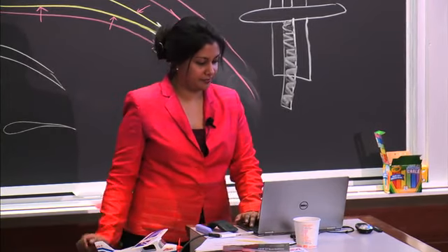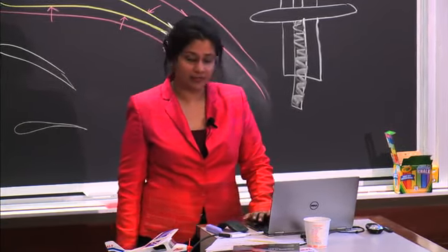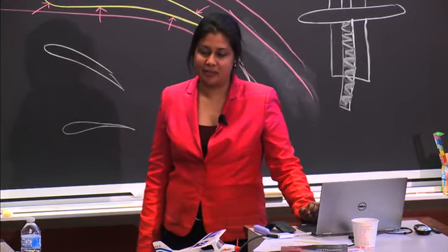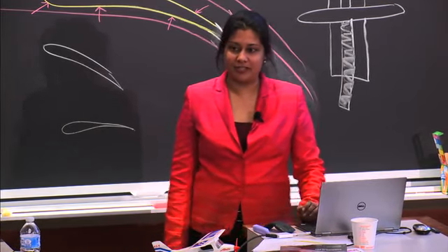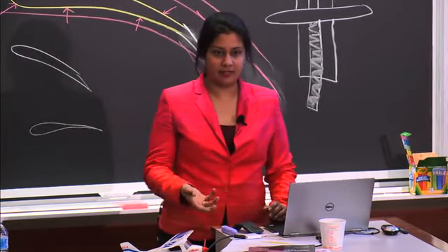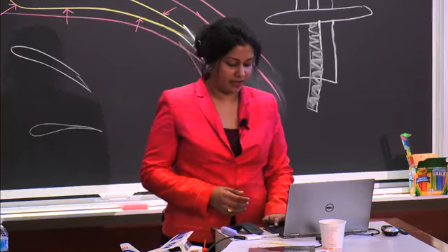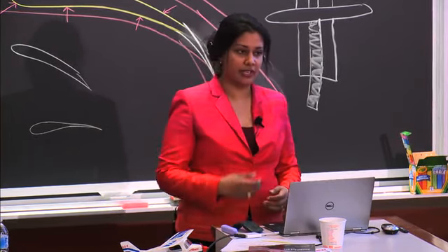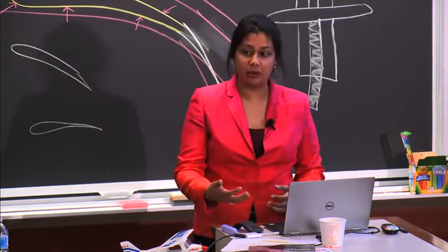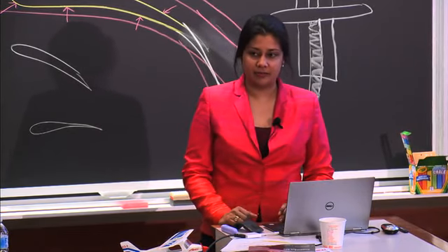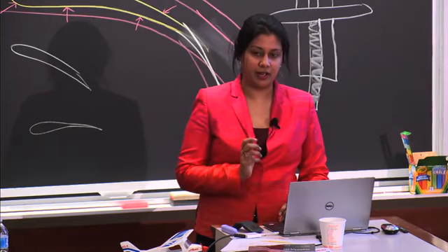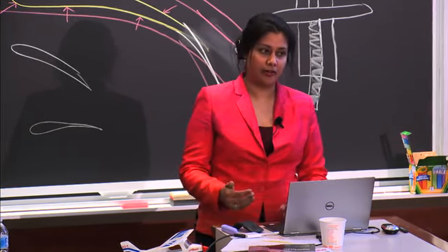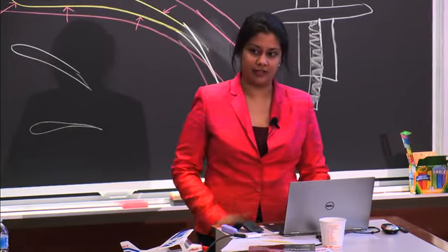Thanks. I have a simple question for you, maybe. Just to help me remember, why is it called P factor? What's the P for? Power or propeller? So the P is referring to the propeller, the right propeller more than the left. It also usually happens when you're at a higher power. So some flight instructors like you to think about when you have higher power in the airplane, you'll need to put on more right rudder to counteract that left turning tendency.